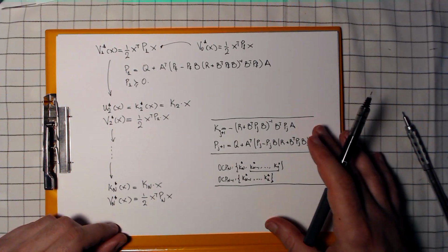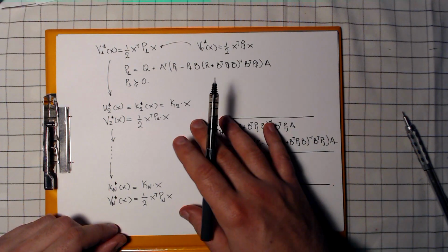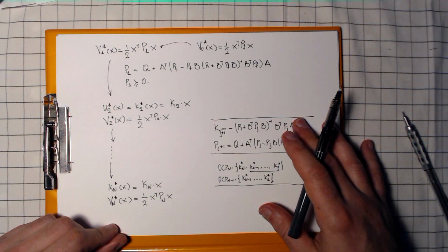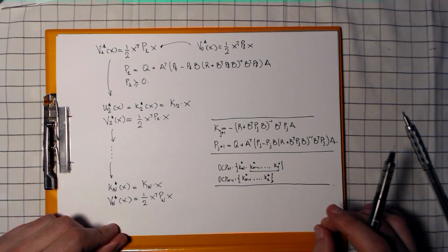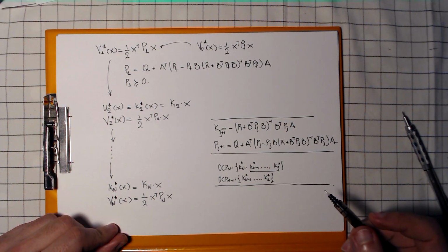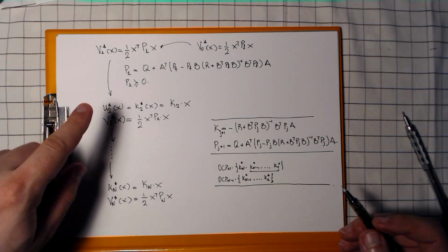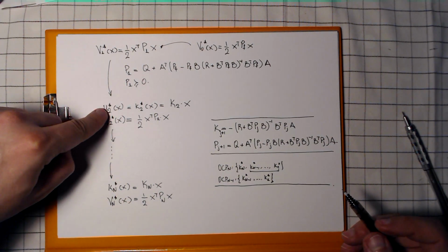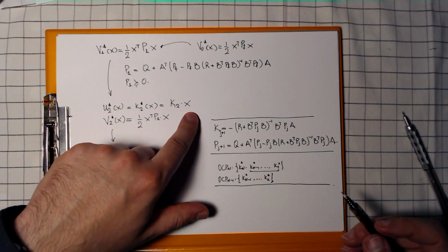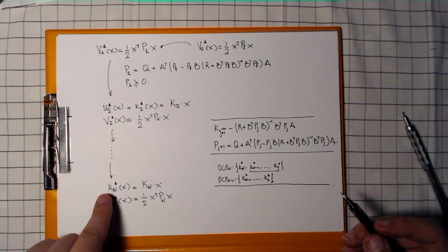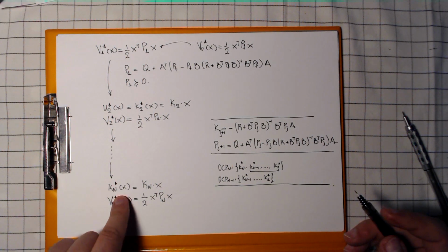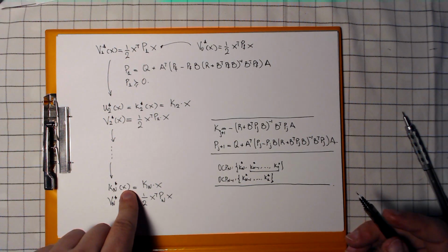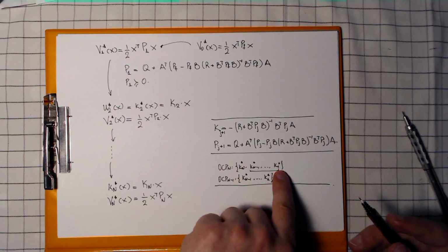And the second thing we need to keep in mind is that dynamic programming produces optimal policies. It doesn't just produce a sequence of optimal control actions. It produces functions. You see here, u2 star is u2 star of x. This K2 times x is a function of x. And kappa n star is again a control law, and this defines a control policy.